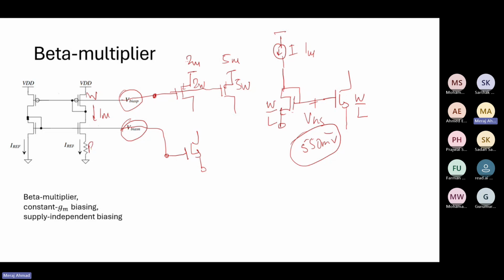And this is a resistor R. I will not go deep into how a beta multiplier works. It is in any book or course, but from a design point of view, what are the important parts? What are the equations which can guide us? If you see, this is your VGS1 and this is your VGS2. The unit element we have selected, WP by LP, and you have WP by LP the same here.